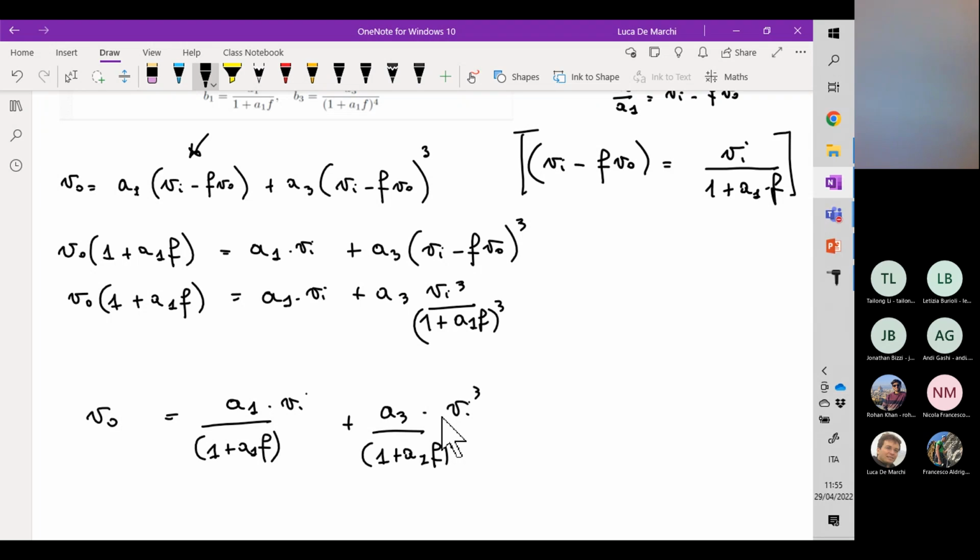Suppose that the initial gain of our amplifier is provided by the black solid curve. This one. You see the transfer function associated to this A of j omega has 3 poles. And each pole induces a phase shift equal to 90 degrees.